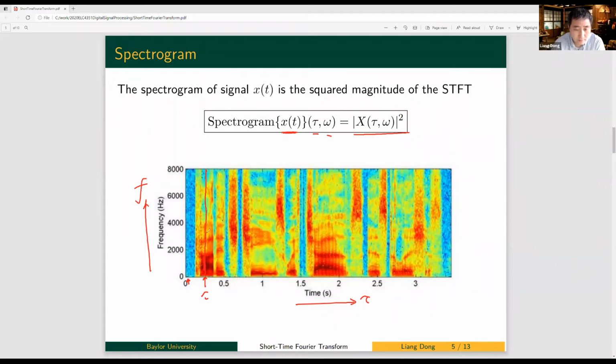And then if we change to this time instant, another tau 2, this is tau 1, we see we got some hot color here at higher frequency, about 3000 hertz. So the frequency indeed changed. And we are using that to capture a dynamic picture of a spectrum, of a spectrogram. So you can imagine if in a practical system, this entire spectrum can roll out. It can shift as time goes by. It can shift because you are taking a short-term window and you take that all the time.